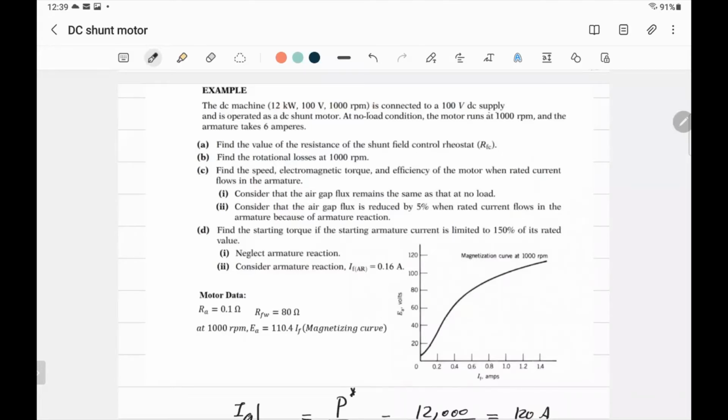You did in the lab the two things, dynamometer in prime mover mode and brake mode, and you found you don't have anything hooked to it, but you found that there is a power, there's a torque. This is to supply the loss, the friction loss, the mechanical loss, the rotational loss, because there is a shaft, so this needs power, right? So in no load, it just supplies the rotational loss.